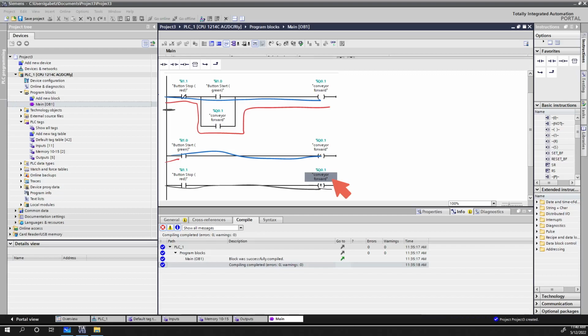There is one weird thing that you have to remember about this, though, and that is if you're using a traditional output, like I have up here, traditional assignment, no set or reset, you may use that output name as an output one time in your code. All right. Down here, if you're using your set and your resets, you can use these as many times as you want in your code, and it will work just fine. So it is definitely something that you need to be aware of.